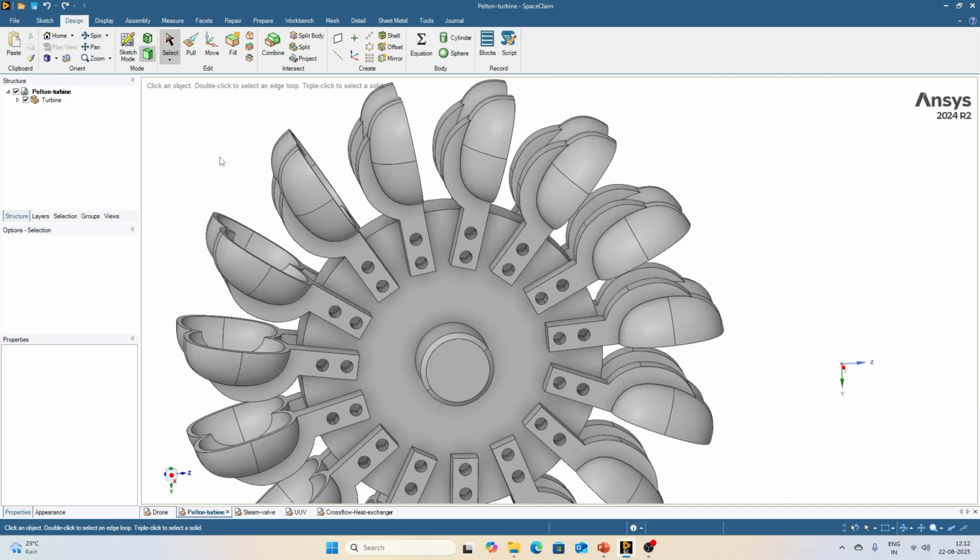This was about selecting. If you want to remove any object or any geometry from the selection, then you can just click on that object one more time and it will be unselected. So for example, if you selected these three faces using the control key, and if you want to remove one of those surfaces, then you can keep the control key pressed and click on the face one more time,